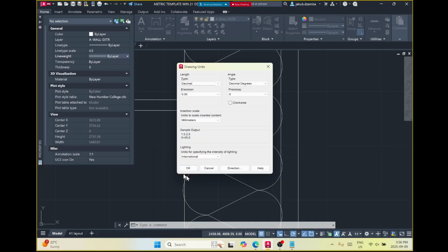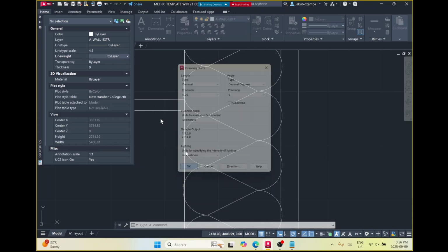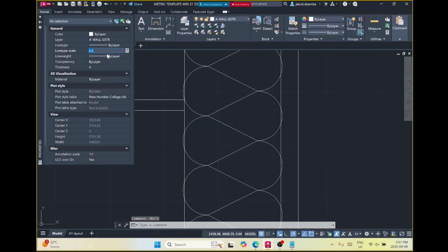And this will let you change the units of the drawing. So for instance, my unit, the precision was set to 0, not 0.0 or 0.00. So I can then change it here and say I want 2 decimals of precision. And then it lets me do things with greater accuracy. Not a big deal, and it's something we'll run into more times. So you'll get familiar with these different commands by using them more and more times.